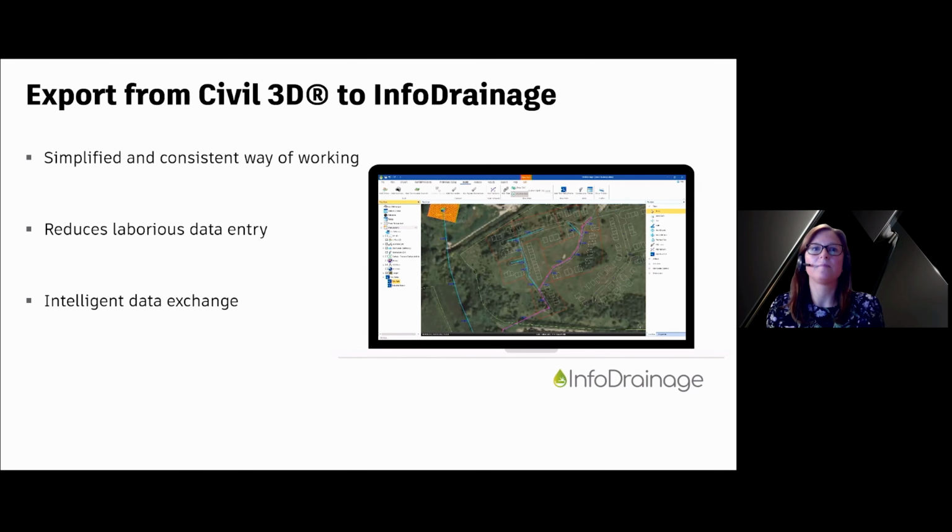This next video shows a later stage in the design project where we're importing updated pipes as well as more complicated green infrastructure elements, which we refer to as stormwater controls in InfoDrainage. So again, we're using the InfoDrainage for Civil 3D ribbon. We've selected the InfoDrainage import from InfoDrainage option and use the parts mapping manager, in this case, selecting a file that has been saved.